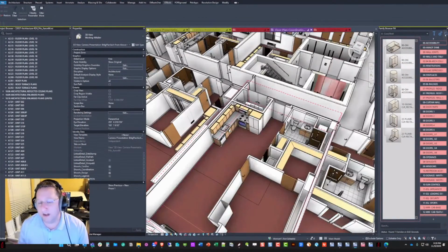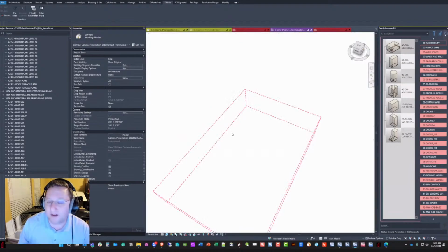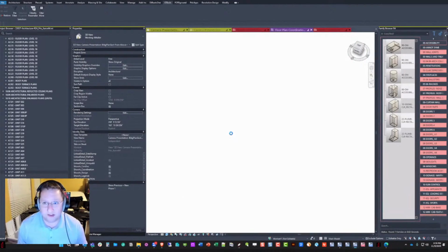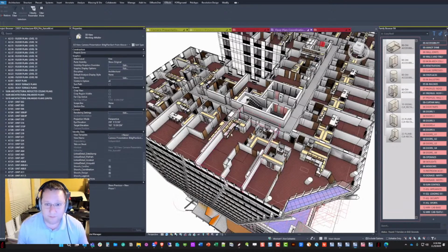We will do reductive LOD. So at coarse level of detail, some stuff will disappear. I will not model in a separate piece of geometry for coarse level of detail, because now I'm carrying around another bag of luggage, right? So we'll remove stuff at lower levels of detail, but I really believe in just having clean geometry for everything, and not having 16 masking regions and lines in every view of the family, and then just relying on the awesome development team to make performance get better over the years. If you're not aware, 24 is 20% faster at regenerating a view.